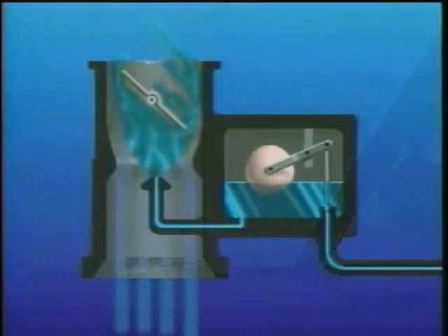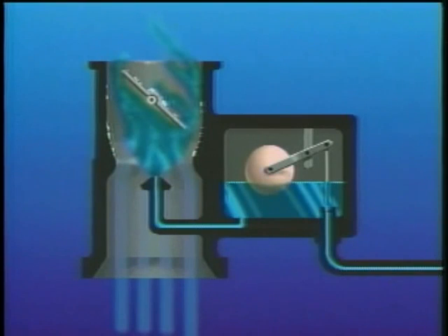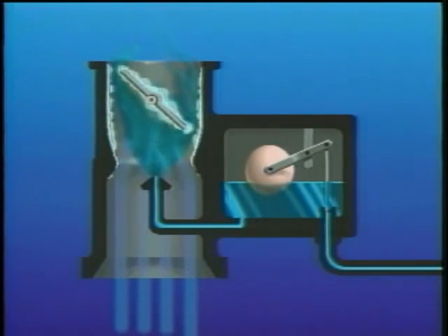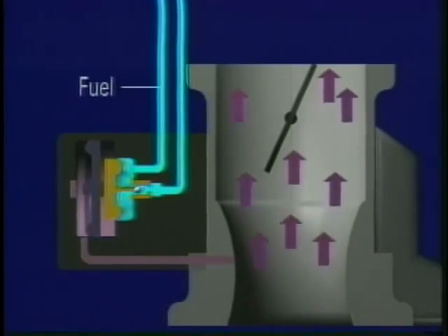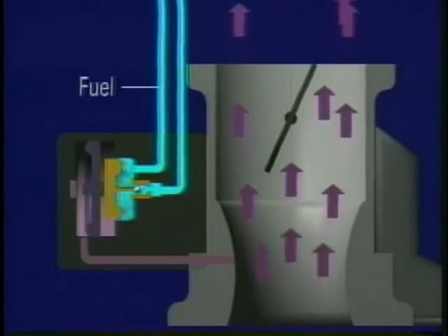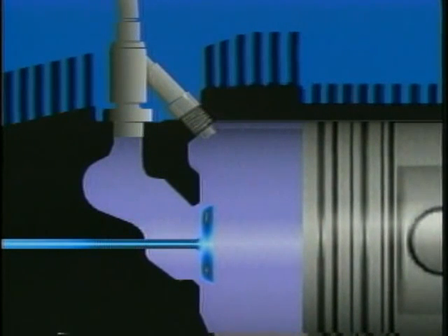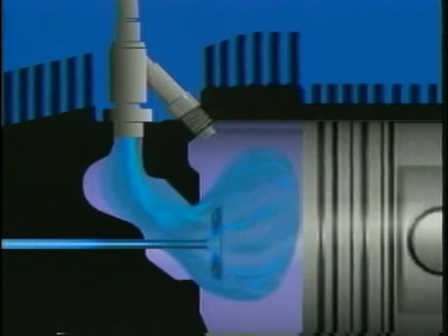Another advantage of fuel injection is that it is not susceptible to carburetor icing. Float-type carburetors are highly susceptible to icing due to where vaporization occurs. As intake air passes through the venturi, it cools. Further cooling occurs during the vaporization process. This drop in temperature can cause moisture to freeze and adhere to the internal parts of the carburetor. In a fuel injection system, there is no significant temperature drop across the throttle valve, so icing is unlikely. In addition, the fuel is vaporized at the cylinder head, where increased temperatures make icing virtually impossible.